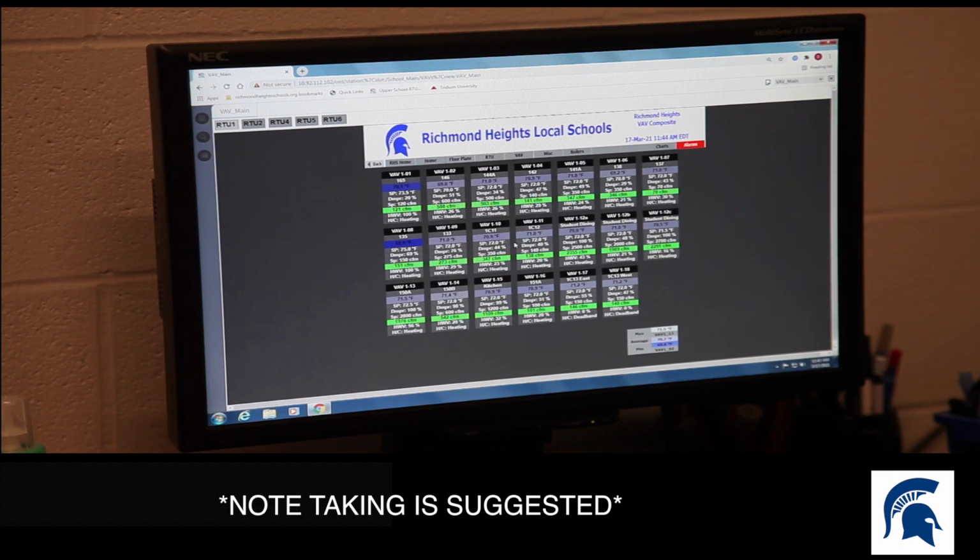It looks at the scheduled start time, outside air, average room temperature, and a comfort deadband, which I think is like 69 to 75. It does calculations every day when it starts up to say, hey, I need to start 2 hours early, or I need to start 20 minutes early to get up to temperature before people are actually going to be in the building. So that can end up staggering them.